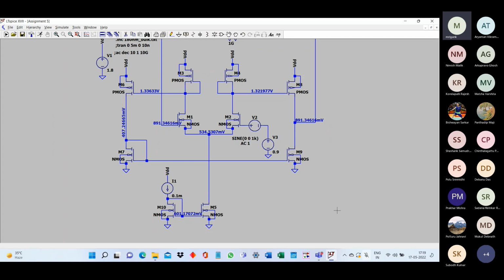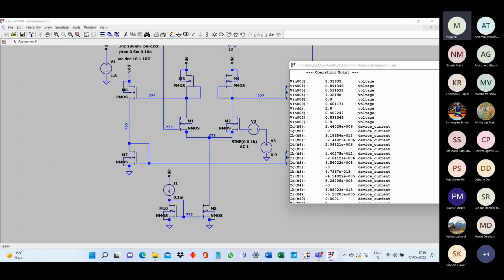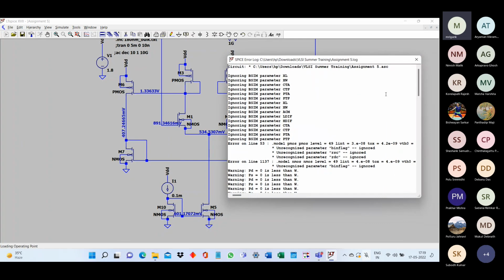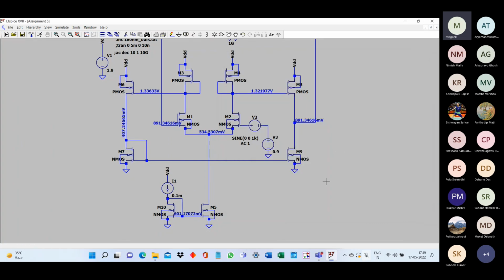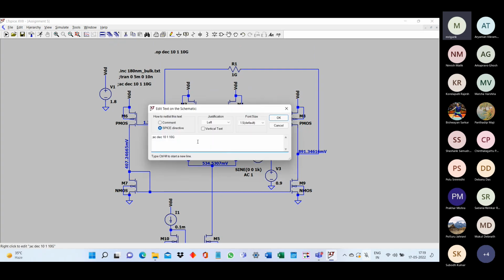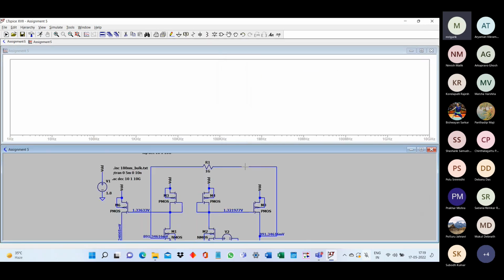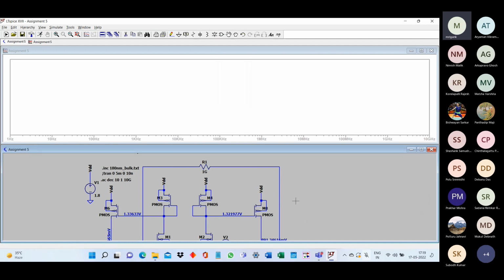Right now, in the feedback loop, you are seeing that there is some error. It is not exactly the same, but the resistor is at least enforcing that the DC values are almost similar. Now, at this particular point, we can try to look at the AC analysis and figure out what is the frequency response. You can make the R even larger. That will become even more ideal, because right now the only purpose of R is to get a DC biasing. That's all.